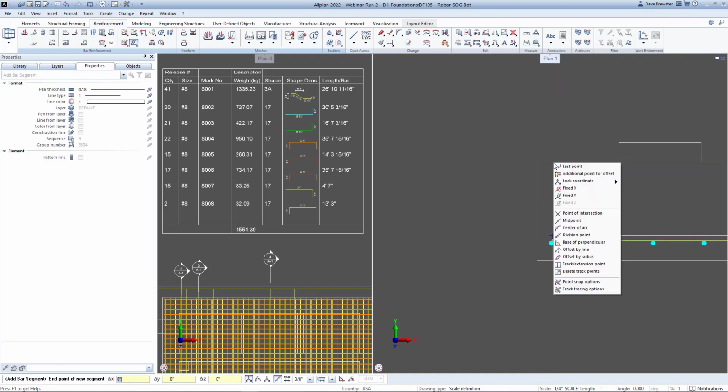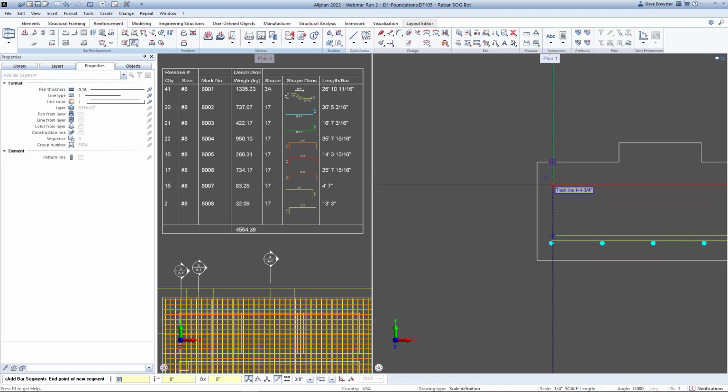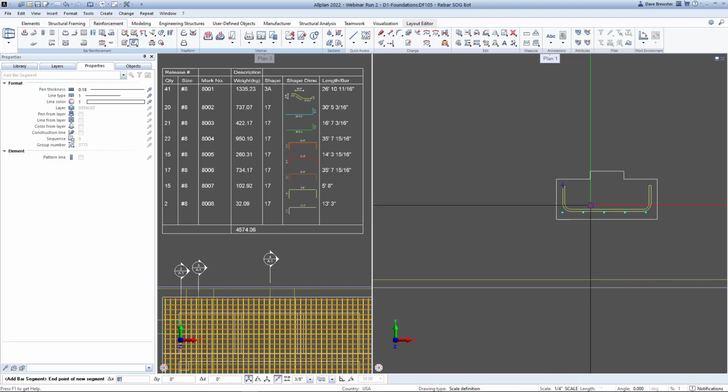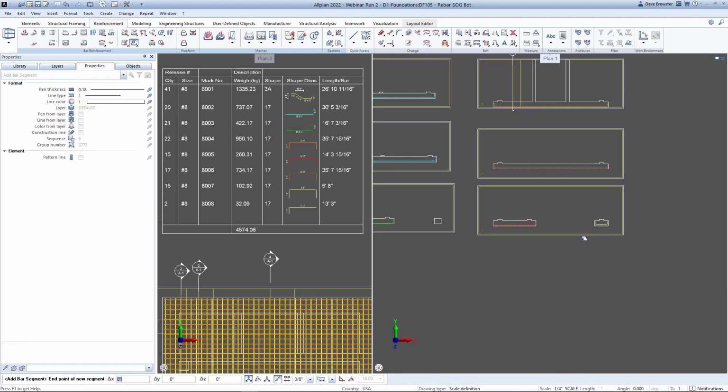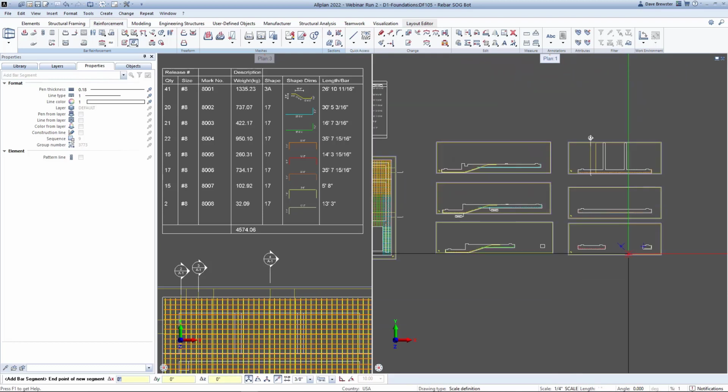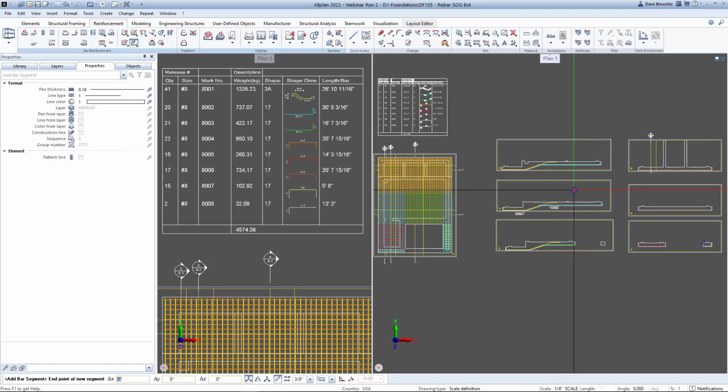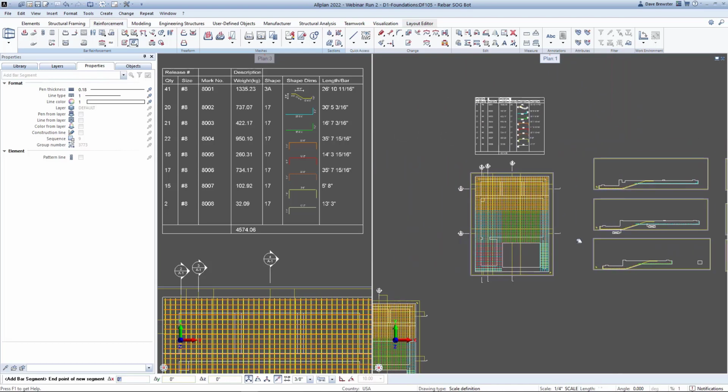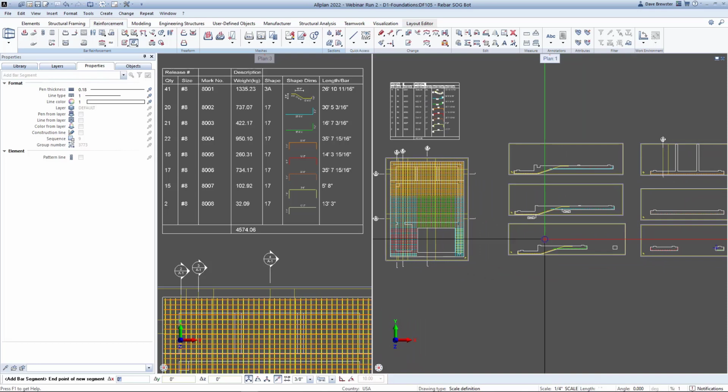I'm going to add a leg to the bar, give it a cover from the top. I'm doing a tracking from the top of the concrete, give a cover of 3 inches, and now I have those bars that were type 2s or type 17s, depending on which company you work for. I've now turned them into general type U bars, type 17 bars.